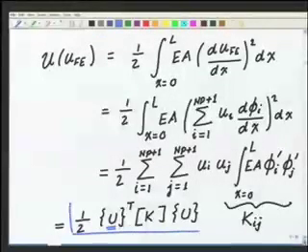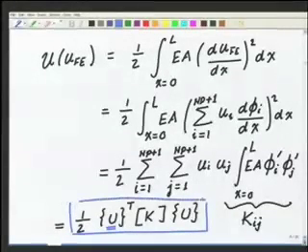So all I have to do is take this product. This is the strain energy of the finite element solution. So this is very easy to compute. And certainly, when one is writing a code, it is healthy practice to do these checks. Create problems for which I know what the finite element solution should do, and then check whether my code is really doing that or not.